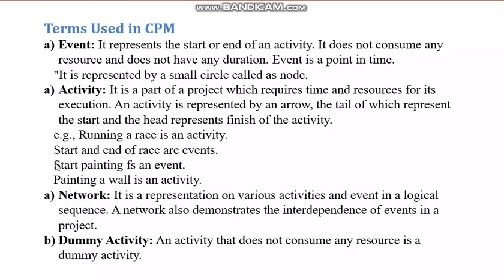Okay, now next, the terms used. Now I just said we'll see the definitions. The first definition that we see is event. An event represents the start of an activity or the end of an activity. Like you started digging the foundation, that is an event, and you finished digging the foundation, that is an event. But in the middle, what you are doing, digging, is an activity. So if there is an activity, on either side of it there will be events.